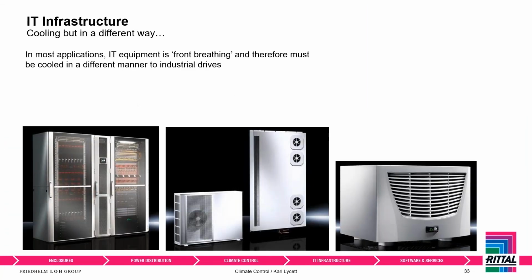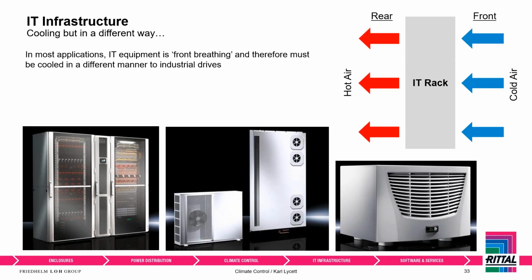Okay, so very brief again. I'm going to do a separate webinar on this, but IT infrastructure, it's cooling, but in a completely different way. The reason it's different is because IT equipment is what's known as front breathing. What that really means is if we look at an IT rack from a side profile, it takes cold air in at the front, it goes through the equipment, and then it's blown out the rear as hot air.